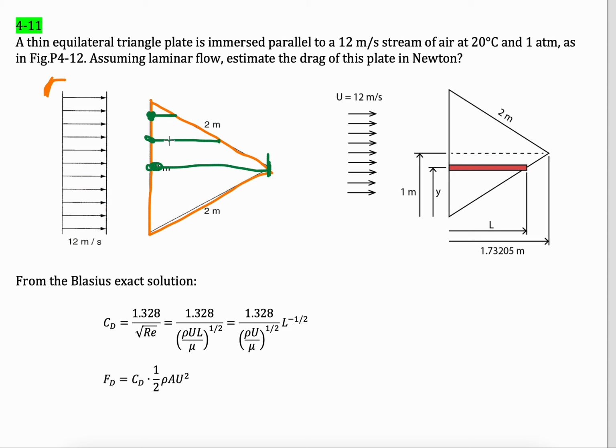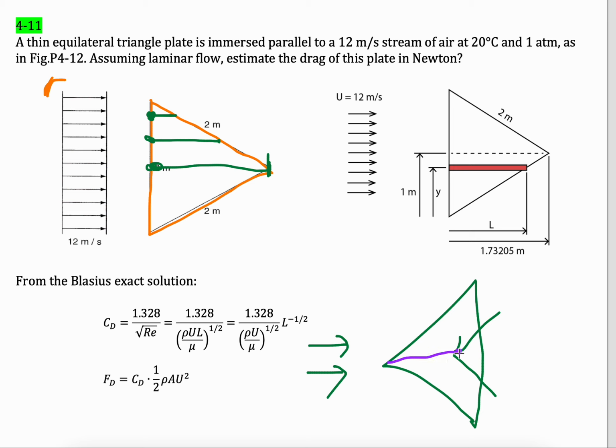Another thing you should understand is, for example, if we have a delta wing aeroplane like this one, with the incoming free stream velocity like this. In a real situation, the laminar boundary layer will change into a turbulent boundary layer, but maybe the change only occurs at the bottom, because the flow from here is laminar and after this point it changes into turbulent.